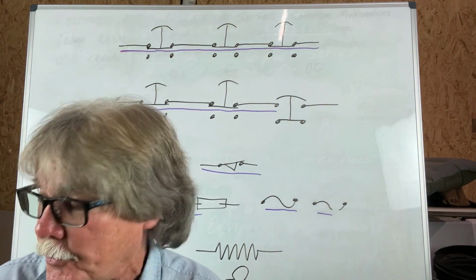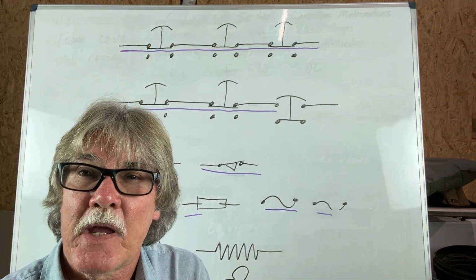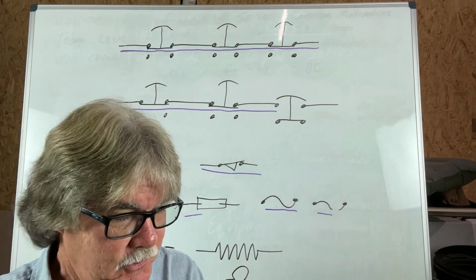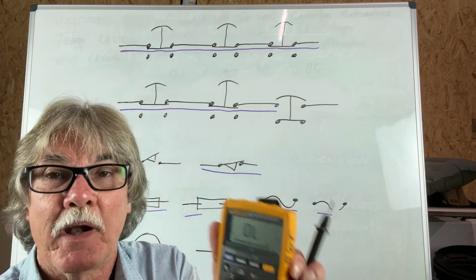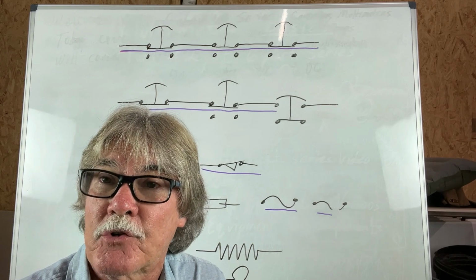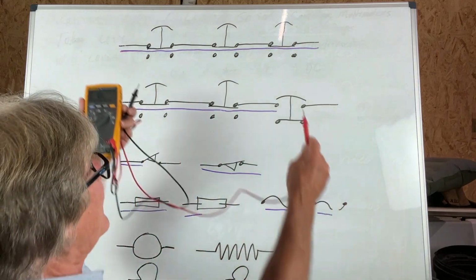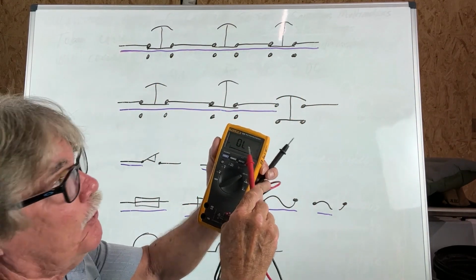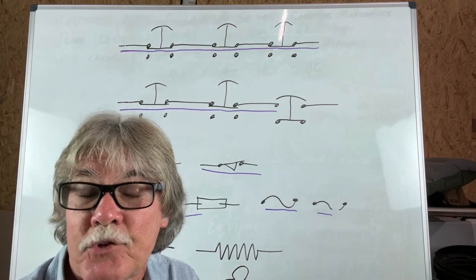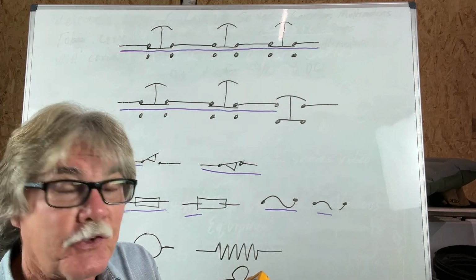That brings up another point I want to address: each meter has its own ranges and capacities. This one says it will beep when it's less than 25 ohms, and it stops beeping when it's greater than 250 ohms. So there's a range right there. In other words, it could beep at 200 ohms if we measure from here to here, and 200 ohms is not really good. So you have to watch your meter, not just listen to the tone.